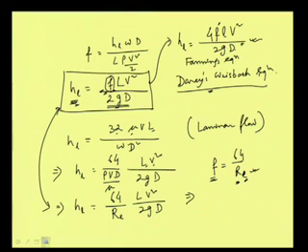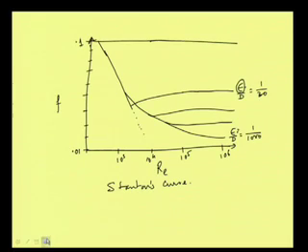We should be very much careful, and when we do not have any other way, we will have to take recourse to this curve. In fact, Moody has also given some curves. Moody's curve is also very popular, and we can use that too. Then we have some explicit formulas relating Re to f. Generally, it comes in the form of 1 by root f is equal to a function, I am writing phi, of Reynolds number and epsilon by d.